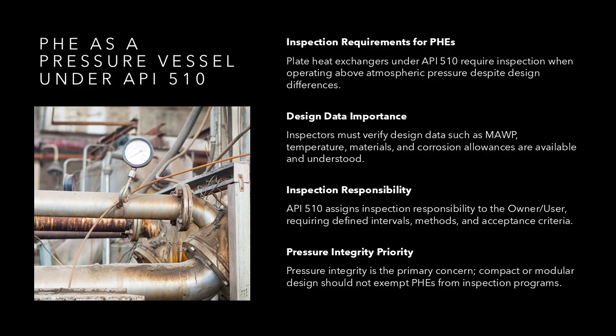This slide explains how plate heat exchangers are treated under API 510 when they contain pressure. Even though PHEs differ from traditional shell and tube vessels, they are still subject to inspection requirements when operating above atmospheric pressure. Inspectors must ensure that design data, including MAWP, design temperature, materials of construction, and corrosion allowances, are available and understood.